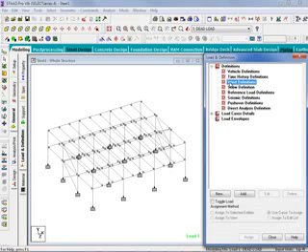For this sample structure, we would require 6 wind load definitions, which will be used to consider the wind load in each global axis direction and for each wall of the structure, such as your windward, leeward, and side walls. For this training course, we will be focusing on generating the wind load definition for the global X direction.